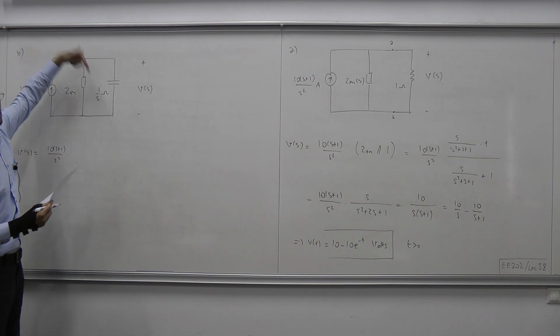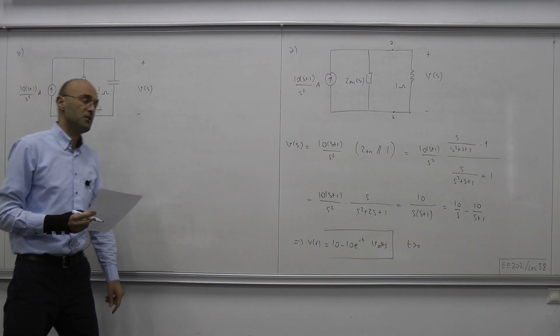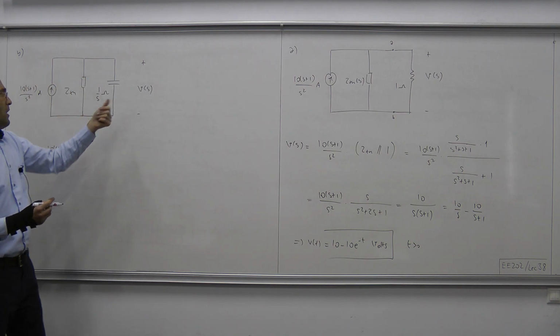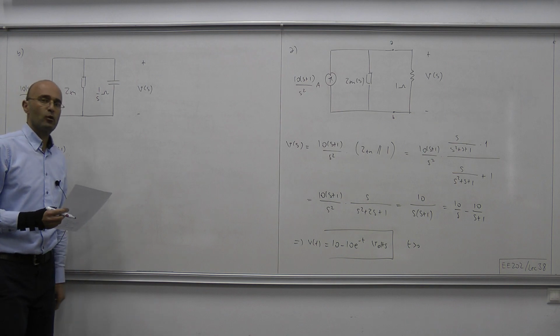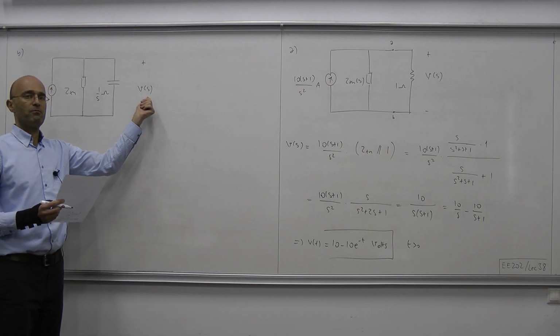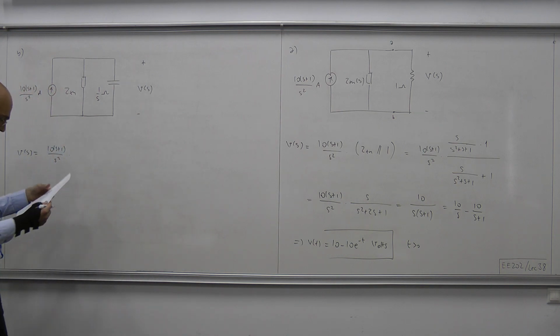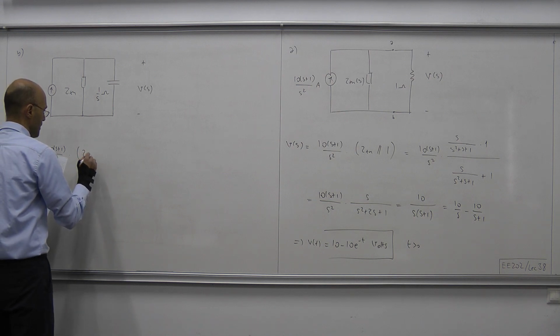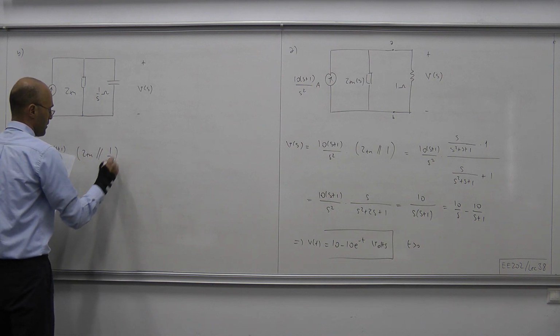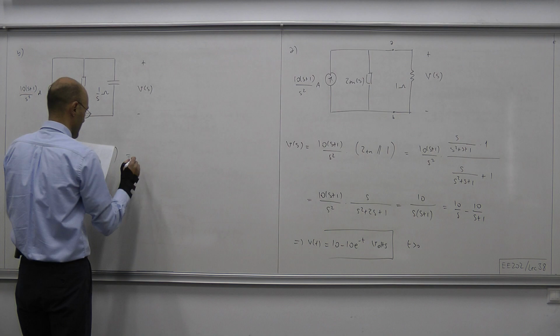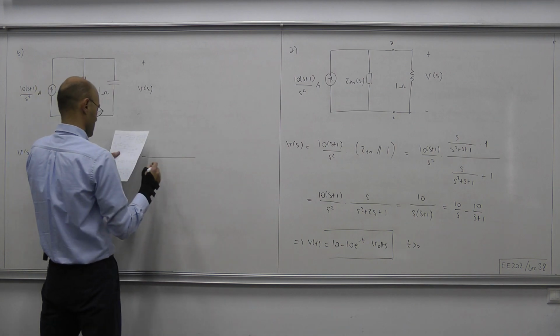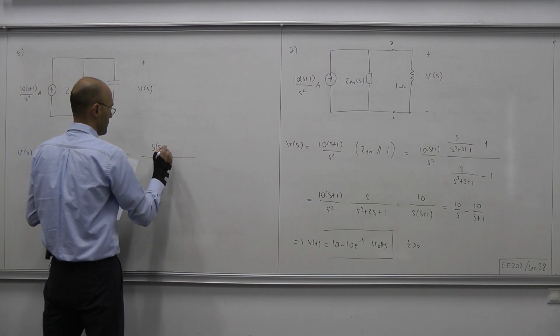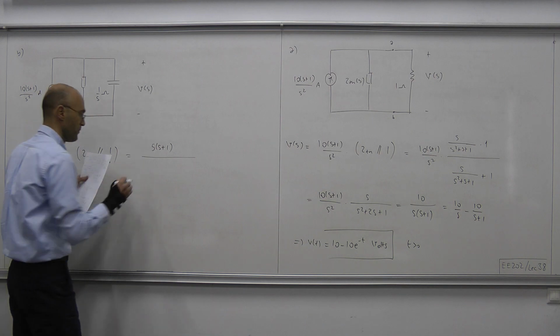Okay, this current will be visiting that equivalent impedance seen by the current source. And then the current times that equivalent impedance generates this voltage. Z Thevenin in parallel with 1/s. And that produces the following rational function.